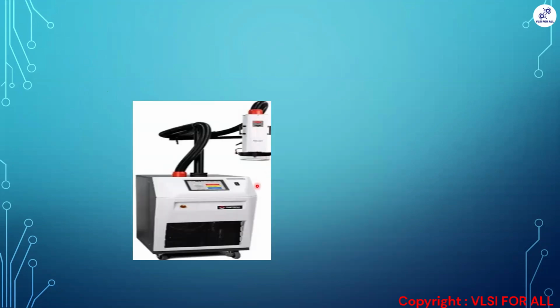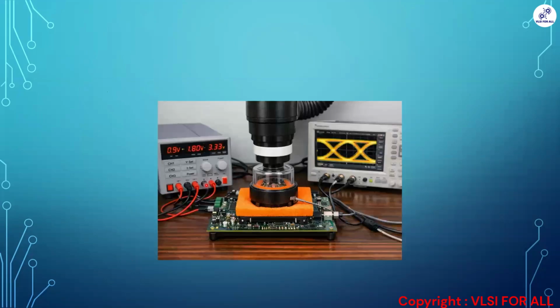Here we will be setting some temperature like 50 degrees, 60 degrees, 70 degrees. Using this, a sponge will be there. We can't directly keep the thermal cap on the validation board. We'll use some thermal sponge here for safety, and we will be placing the thermal cap on the sponge. And in the center of this, you will be having the SOC.